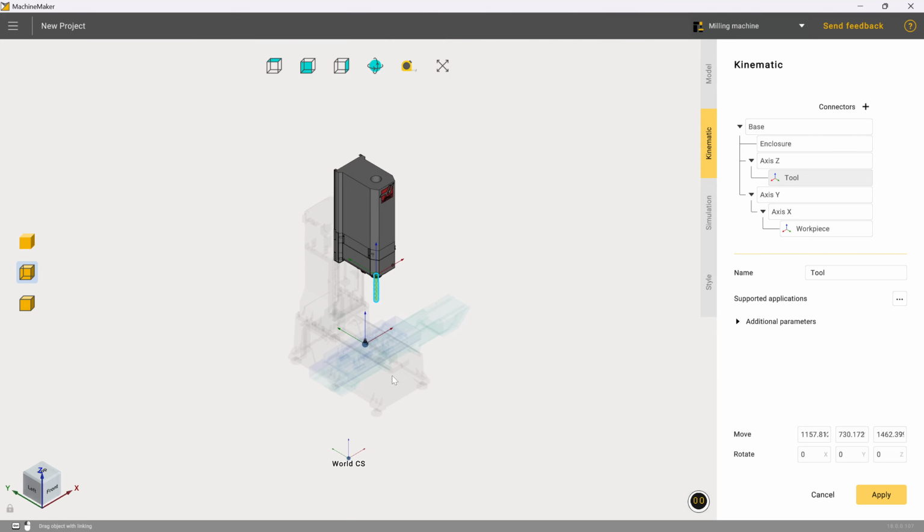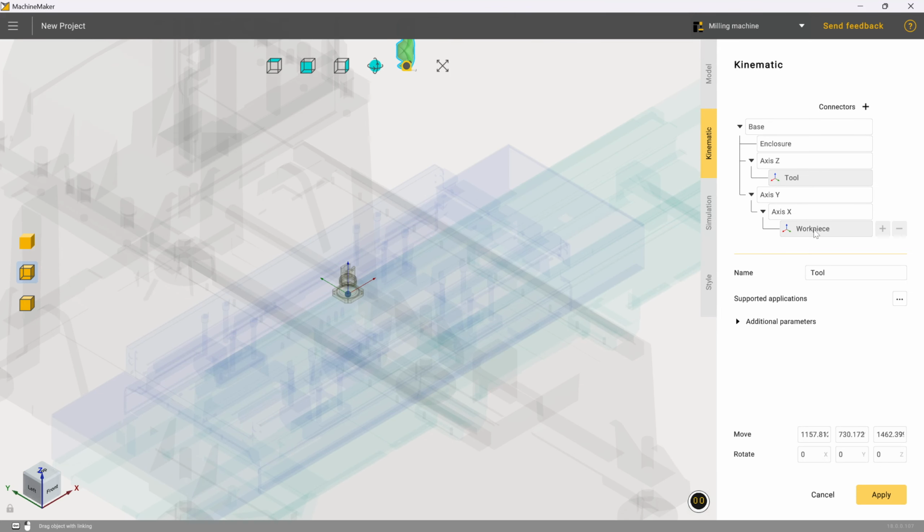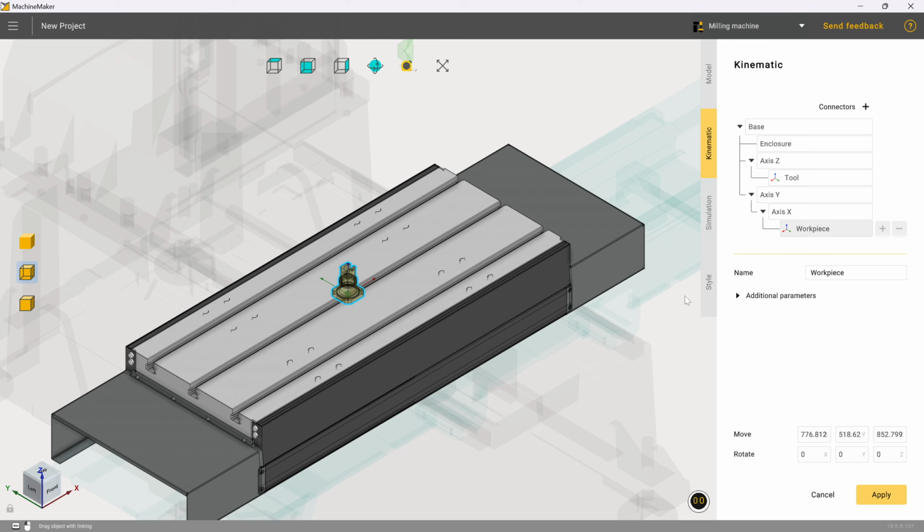This is where it gets a little bit interesting. Now, obviously, where you define your workpiece is a very personal kind of decision, let's be honest. Putting it into the center of the table is very traditional, very workable. I also like to work from the bottom left as well, and I like to set up my workpiece definitions based around the center point of the T-slots, because when you're putting down large vices or whatever, you'll often have tenon keys in there to align it accordingly. And it's just a handy little reference.